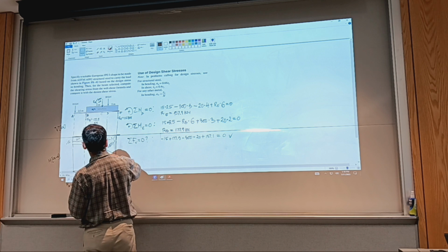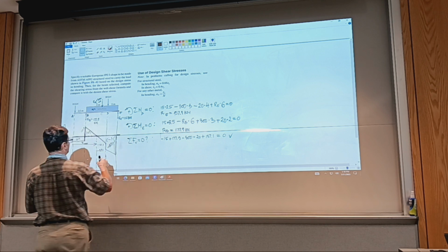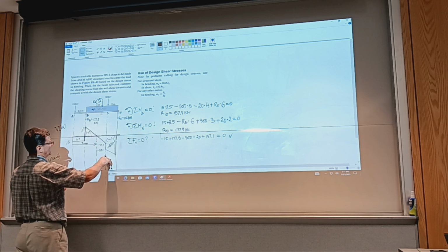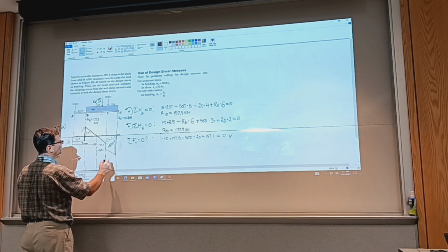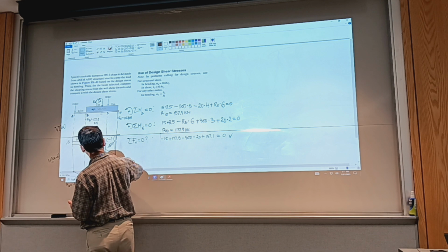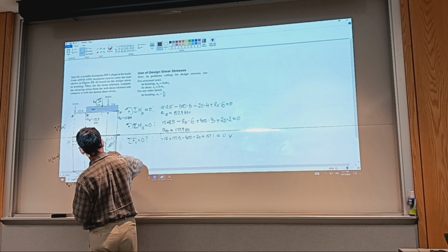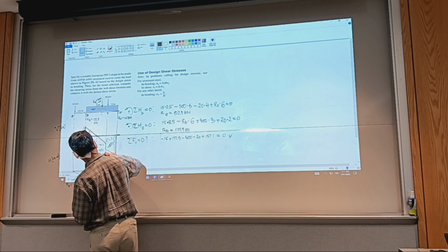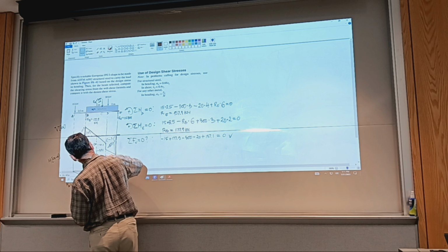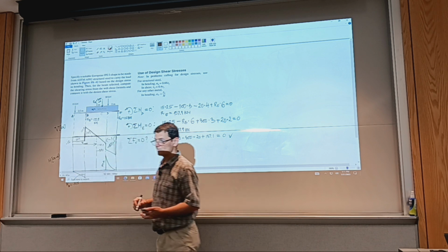And as for the slope, it starts with a negative slope that is big and goes to a zero slope. It cannot go this way, because it would go from a positive slope to an even bigger slope, so it has to be this other way, this branch, for the last section of the moment diagram. Does it make sense?